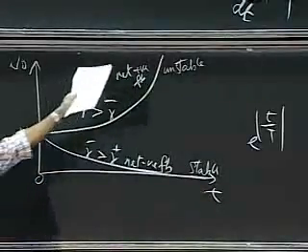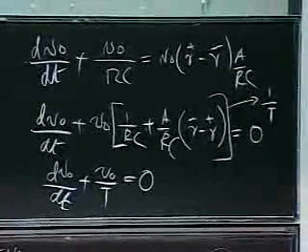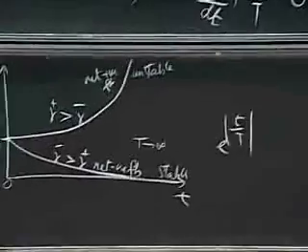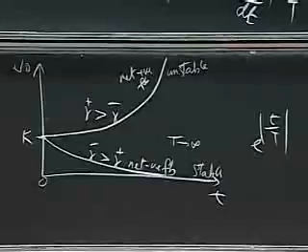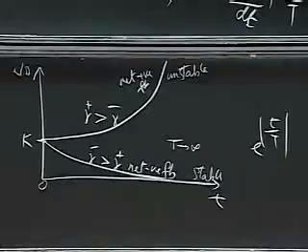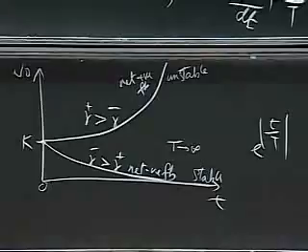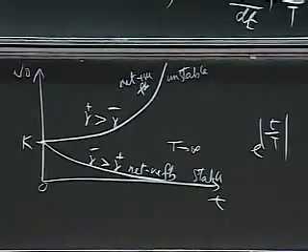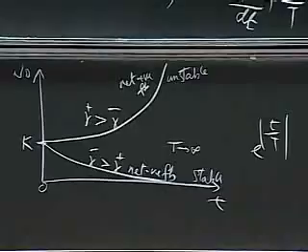What happens when capital T goes to infinity? Spend 5 seconds thinking about what it means physically. What does it mean for the time constant of an RC circuit to go to infinity? That means that your R and C are very, very large. That means that the circuit is going to be very sluggish. Think elephant. Big time constant. I want to move a leg, it takes a while to do that. Think big time constants. Everything's going to happen really slowly.